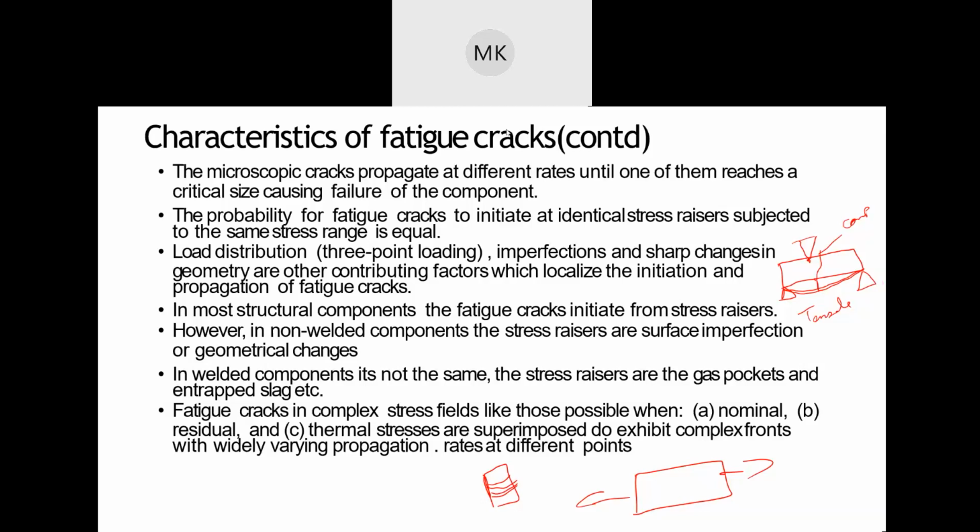But when I keep adding all the temperature effects, the residual stresses in the material, which are due to any processing that I do, all the residual stress on the surface that I can have, and also the environment, all these things are going to change the rate at which the crack is initiated and propagates in the material.